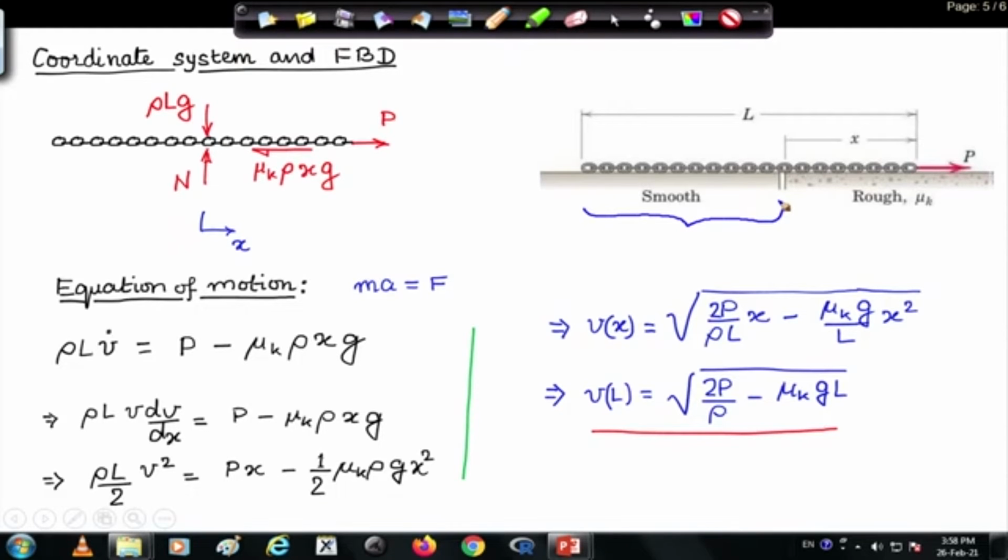If acceleration becomes negative, which means the whole chain starts decelerating, this part of the chain will never be able to feel that deceleration, because the chain cannot transmit compressive force, it will collapse. Therefore, the condition that this chain should not collapse is that its acceleration should always be a positive number, it should always have a positive value.